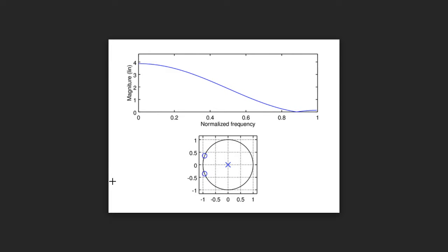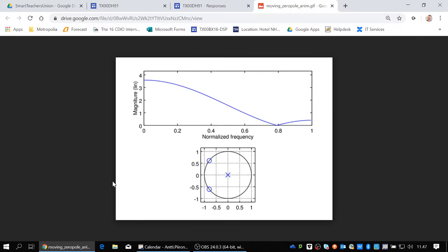If you have just a single frequency, you define the Q factor and bring the pole close to the unit circle at the required angle, and then adjust the Q factor by moving it closer or further away from the unit circle. Just a reminder, keep it inside of the unit circle, otherwise it goes unstable.